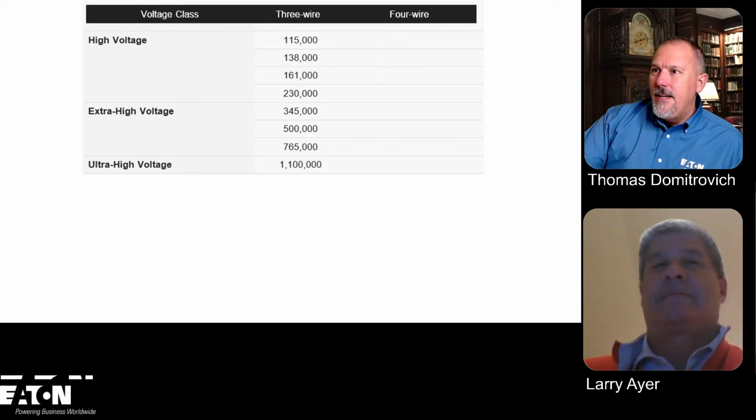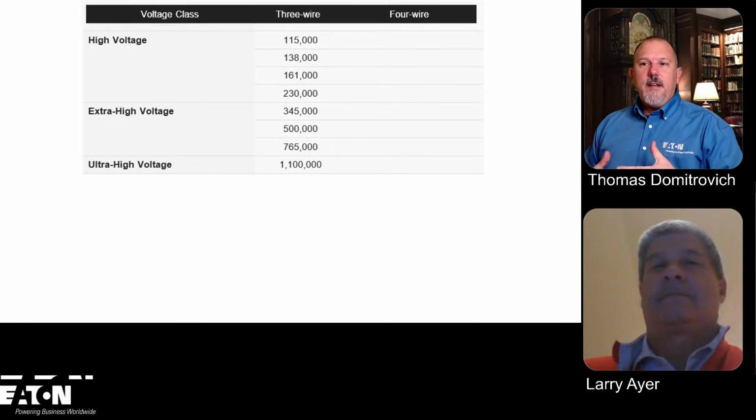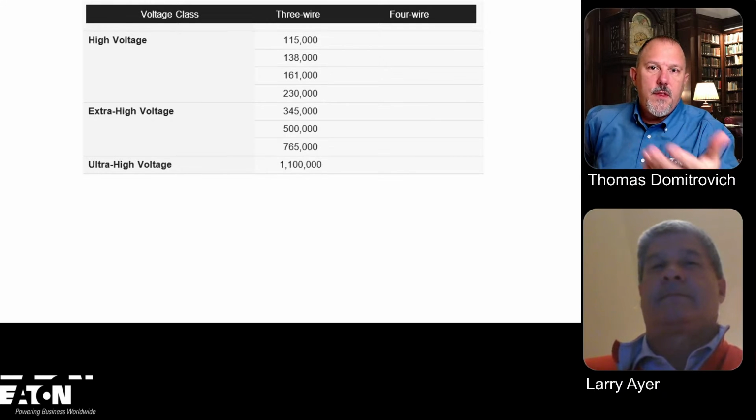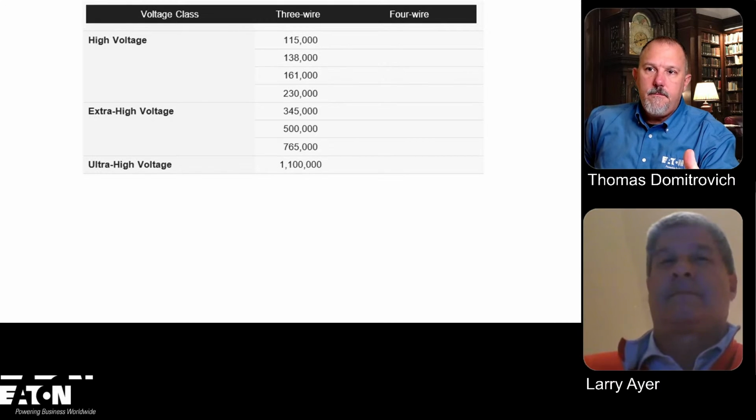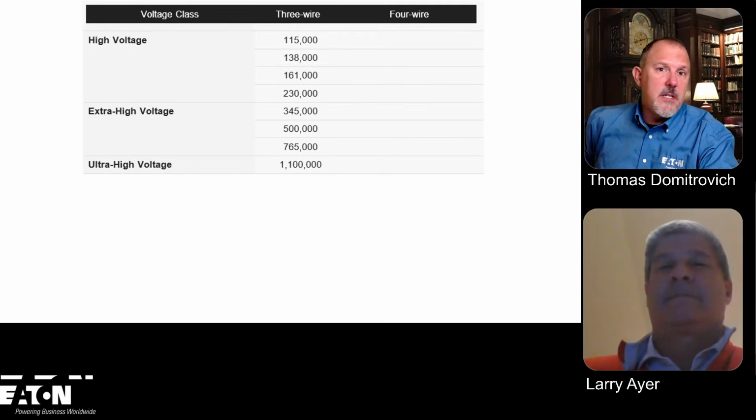This has always been an issue with the NEC. Floodplains consideration, vaults, and other considerations. I had some images of, when you think about medium voltage outdoors, like in downtown New York, down in the vaults, they put those breakers and those switches in submersible type equipment. That's equipment that's designed to be submersed.